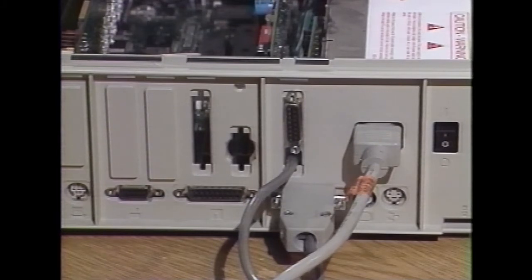The IBM-style keyboard attaches to the female 5-pin DIN connector, which would be installed in this circular port. An analog monitor's DB15 connector attaches to the female DB15 connector you installed in the Apple's backplane. Plug the 19-pin cable coming from the color switch into the built-in female connector on the 2GS's backplane as shown here.